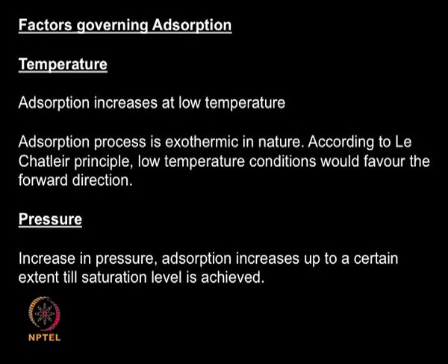So you have to be very careful in maintaining the temperature of the reaction, because it is an exothermic process, and you might have studied in your thermodynamics that for any exothermic process it is ideal to operate at lower temperature. Pressure, we studied in detail just a few slides back, plays a very important role in the adsorption process. At low pressures, an increase in pressure increases adsorption until the whole system reaches a saturation level, and after that the pressure has no effect on the adsorption process. Especially in gas-solid processes pressure is extremely crucial, whereas in liquid-solid processes pressure is not so crucial, whereas temperature will play a very crucial part.